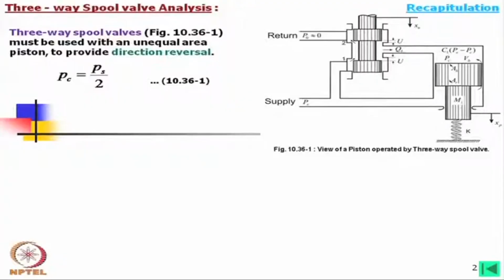That means creating pressure from both sides and moving this. So, for position control as well as force control, it is always better that there is pressure from both sides, and that is why you will find in servo control there is pressure on both sides.